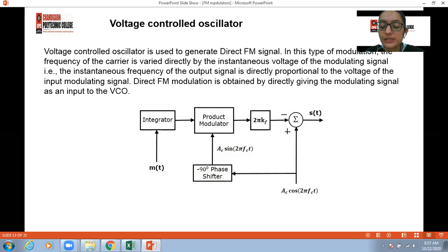Deviations of the transmitter carrier frequency from its desired value will cause the frequency discriminator and filter combination to develop a DC voltage whose polarity is determined by the sense of the transmitter frequency drift.